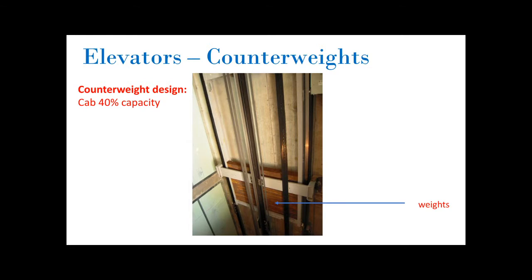The counterweight plays a big role while the elevator is moving. The counterweight is designed to weigh approximately the same as the cabin when it is filled to 40% capacity, which is the optimum design to conserve energy by having equal loads on each side of the sheave.